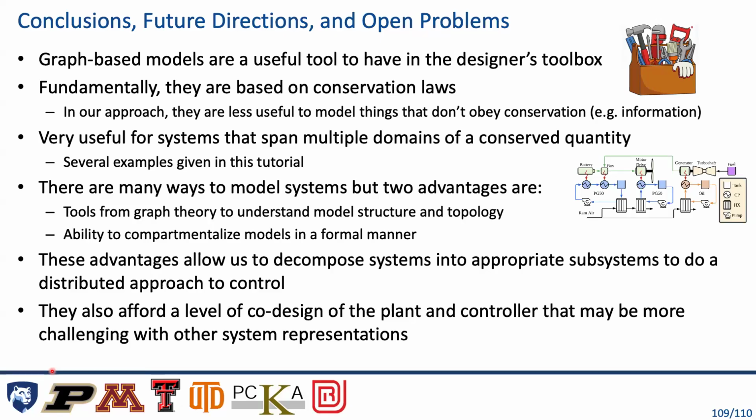If you were to do the passivity from the input to output that you're talking about, it might be that the choice of output you use is not the same physical characteristic as the input. Whereas if you were using these, you might say, well, I'm going to go electrical to electrical passivity. I never think about going electrical to thermal passivity, right? But this gives you the ability to span those types of domains relatively easily.